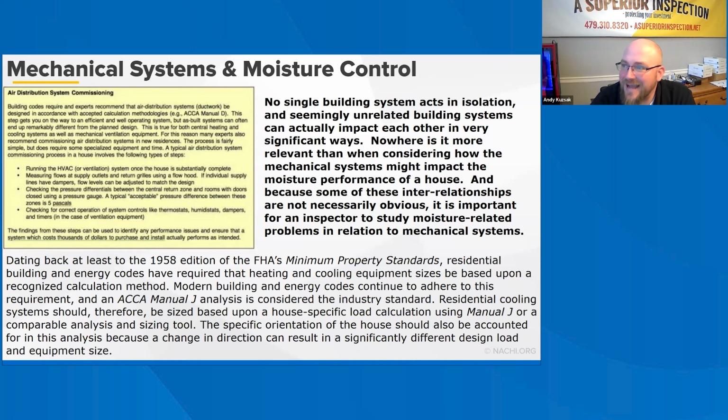floor area, should not be used in place of a building-specific load calculation method, meaning the Manual J. Although still potentially a problem, oversizing of AC systems from using the rule of thumb methods causes increased short cycling of the cooling equipment. Short cycling reduces energy efficiency and can decrease the moisture vapor, latent heat removal capability of conventional AC equipment by as much as 1/2 of the rated latent heat removal capacity. This has two negative effects.